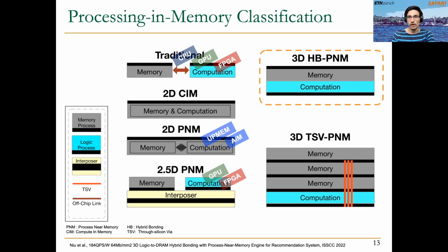Samsung like a 3D design, because it's based on HBM2 memory of course, but instead of having the processing elements in the logic layer of the 3D stack, in reality, we have the PIM units in some of the memory layers. That's why I don't agree so much with calling HBM-PIM 3D stack based processing near memory.